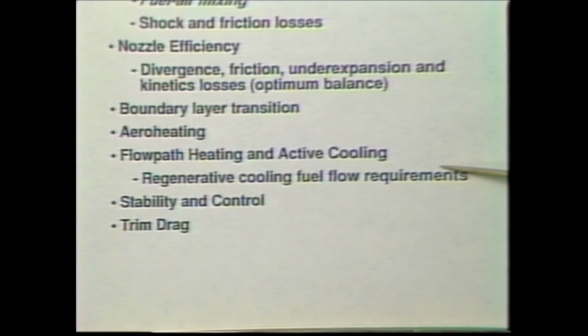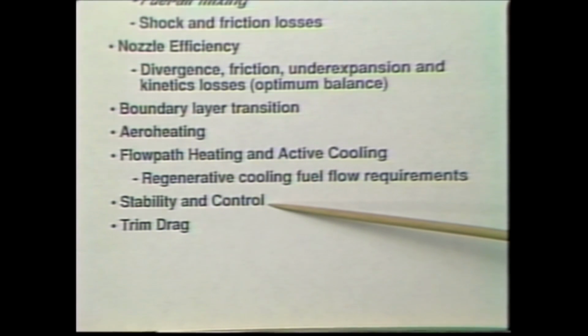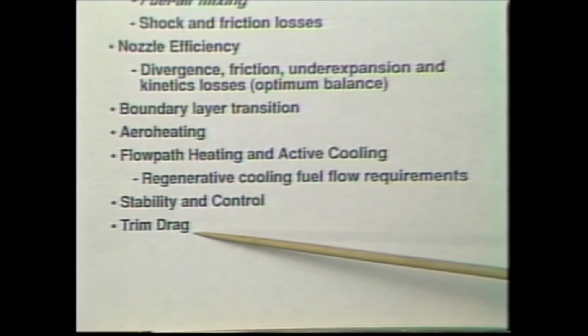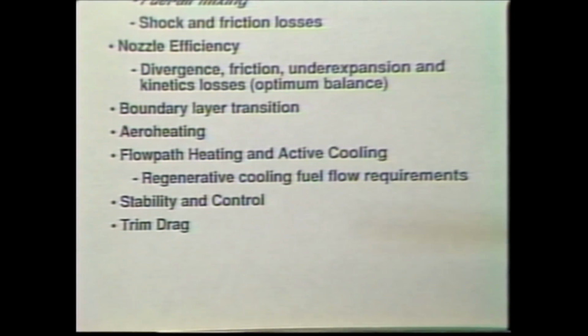We'll see that regenerative cooling, that's taking your fuel, using it to cool your surfaces, adding heat to the fuel, and then injecting it hot, is not a bad thing to do. It helps performance, and it's actually required. Stability and control we already talked about. We've looked at that and sized our wing because of it. And then trim drag. That can be big if your plane doesn't balance out moments by itself, then you have to have your control surface do it, and that introduces drag.